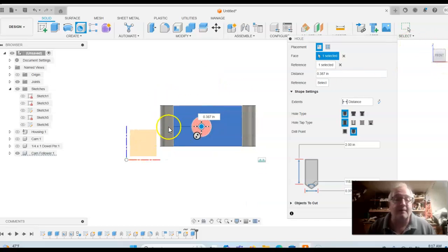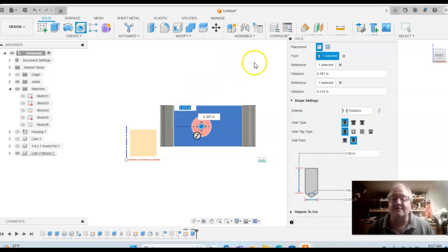So we've got some different sizes here where we would know. We went 1 5/8, or 1 1/4 was the overall length of the slot. So we can put this at 0.625, and that would be centering that in there.